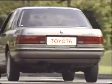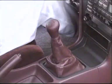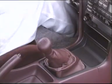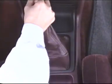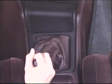No matter what the problem is, identify the trouble using the driving test, and then proceed with disassembly and inspection, checking the parts suspected to be the cause of the trouble. In case of gear crunching while shifting into a particular gear, or more seriously in the case that gear shifting itself is impossible, suspect poor synchromesh operations first.